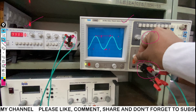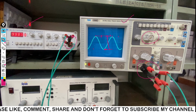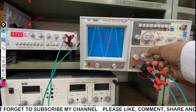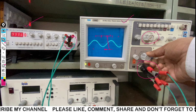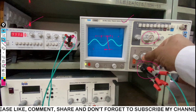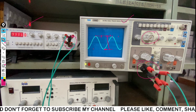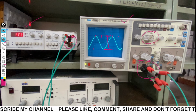Similarly, it is adjusted so that it will give us the vertical divisions, and with this voltage per division knob, as we have seen previously, we can calculate the voltage using these two things. By varying the voltage per division knob according to your adjustment, it will show us the same result, whether it is kept at 1, or at 0.2, or at 0.5. But the waveform should occupy approximately 70% of the screen with two crests or two troughs, and with an amplitude of at least 70% of the screen. Then we can do it.